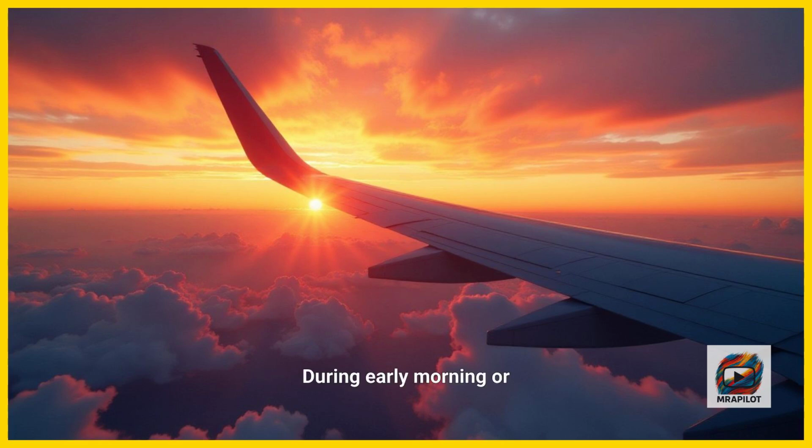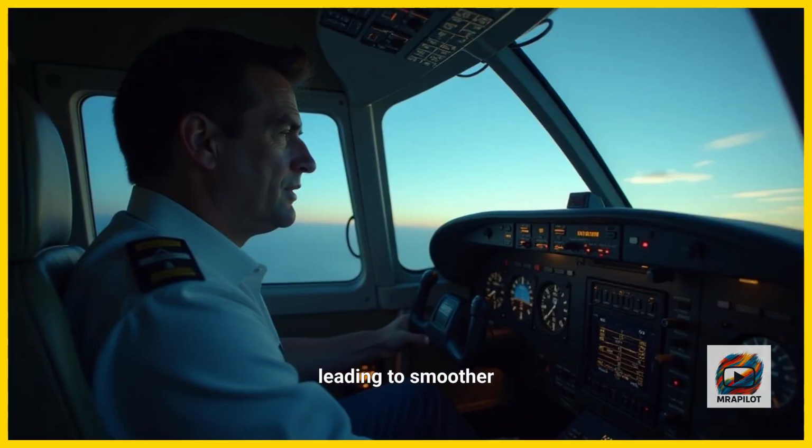Let's not forget the role of temperature in atmospheric stability. Rapid surface heating after sunrise can create thermals, generating bumpy conditions in the lower atmosphere. Great for gliders, but not so fun for passenger comfort. During early morning or late evening flights, temperature gradients are more stable, leading to smoother conditions. That's why many pilots prefer flying during these windows: less turbulence, better engine performance, and clearer air.